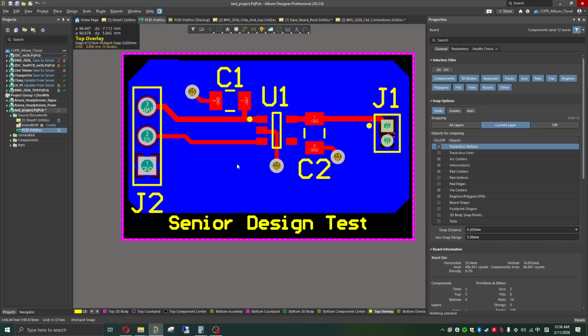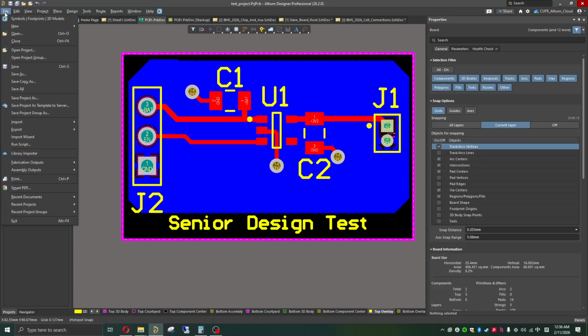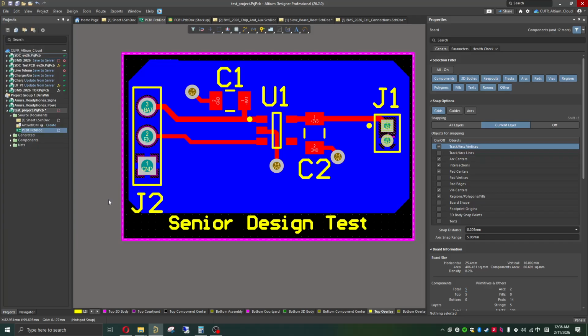I will say that this is going to depend from manufacturer to manufacturer, but I'll just show you where you can get it and where to send your designs. Depending on the fab house that you choose, maybe it's JLC or maybe it's somewhere else, these instructions are really going to depend. But once you're ready to go, in your PCB document, you're going to go to Fabrication Outputs, go to select your Gerber X2 files.